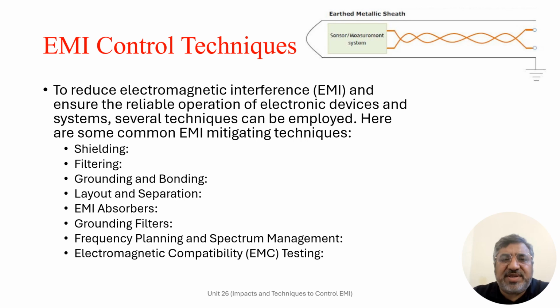can introduce interference. Layout and separation. Careful layout design, especially for components such as power supplies, motors, or high-frequency devices, can also help to reduce EMI.